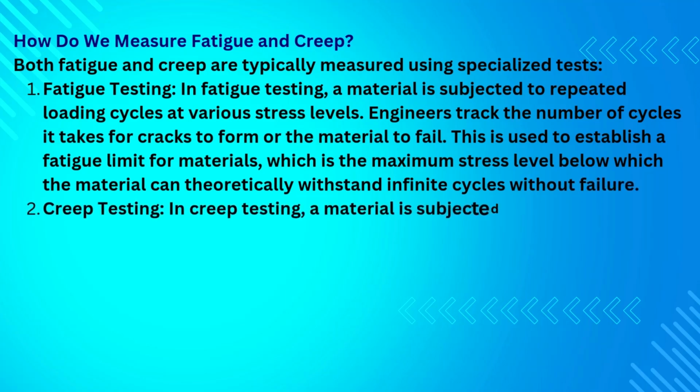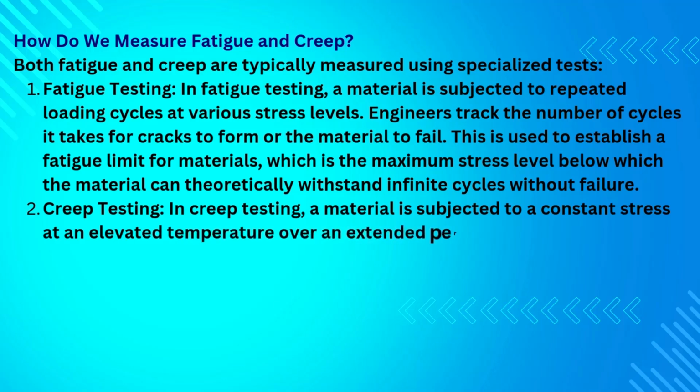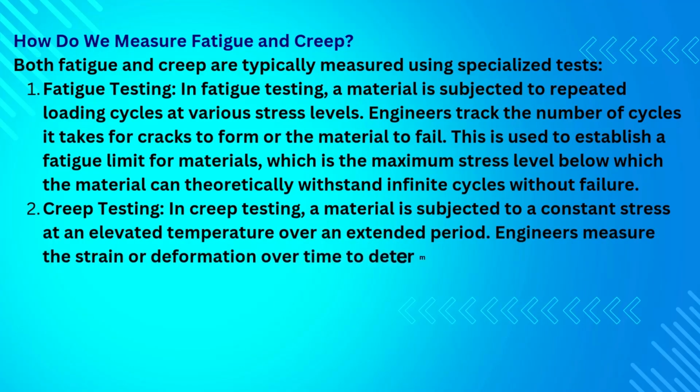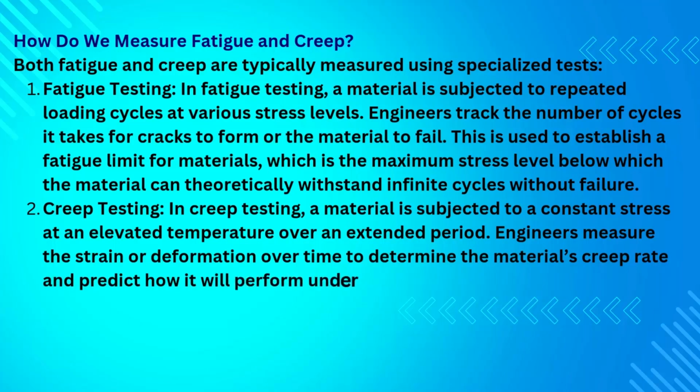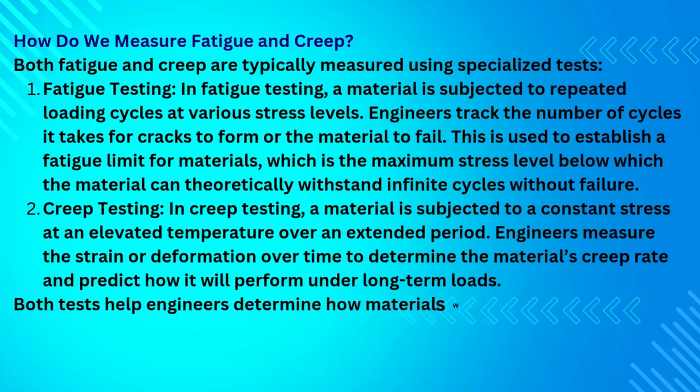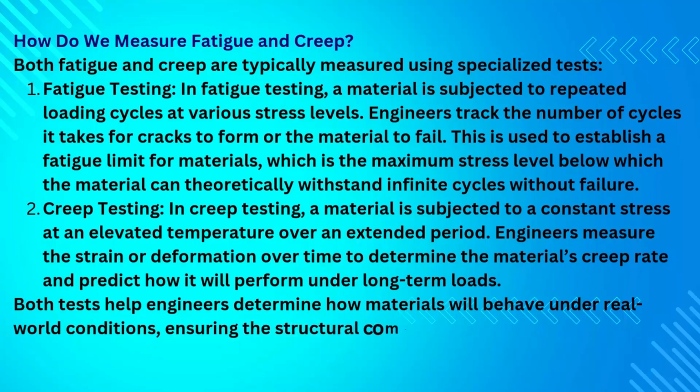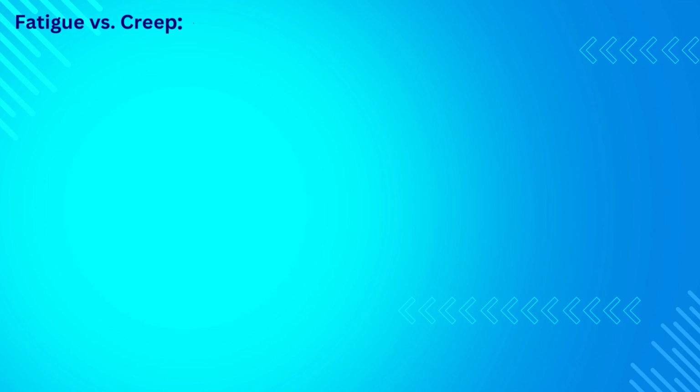2. Creep testing. In creep testing, a material is subjected to a constant stress at an elevated temperature over an extended period. Engineers measure the strain or deformation over time to determine the material's creep rate and predict how it will perform under long-term loads. Both tests help engineers determine how materials will behave under real-world conditions, ensuring the structural components will last for their intended lifespan.